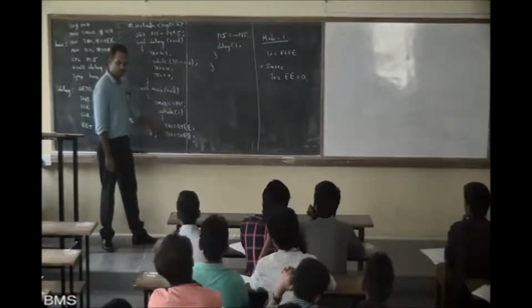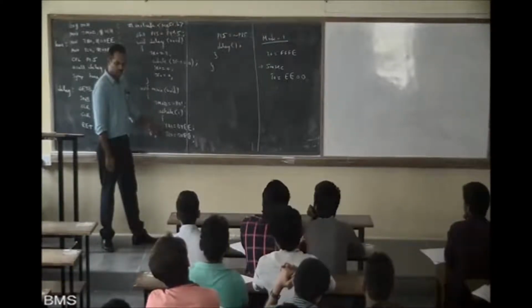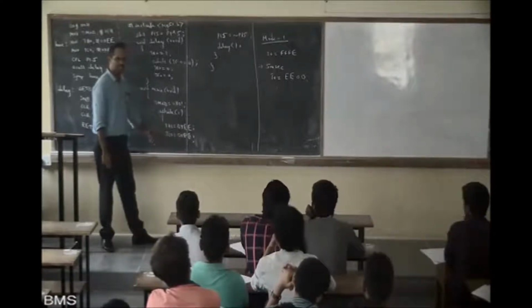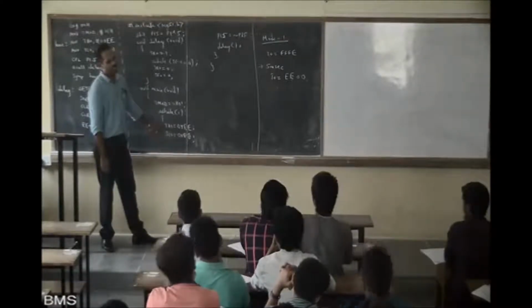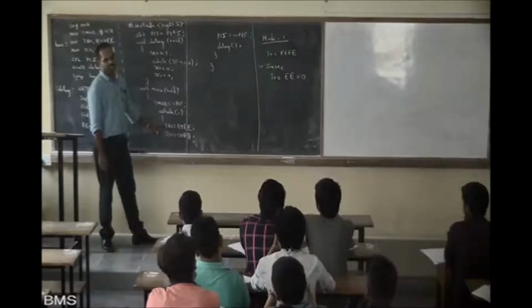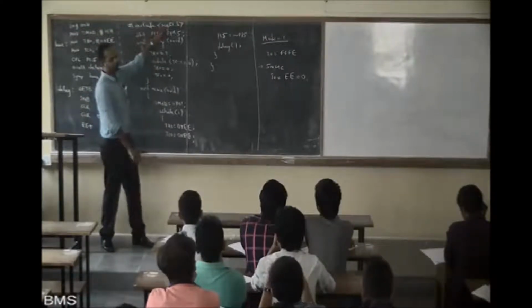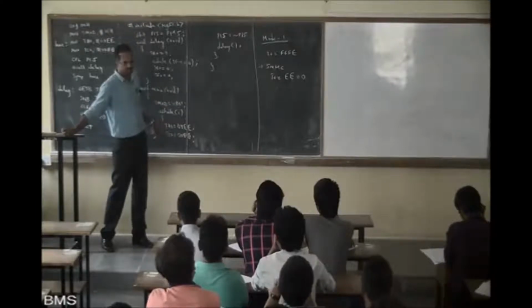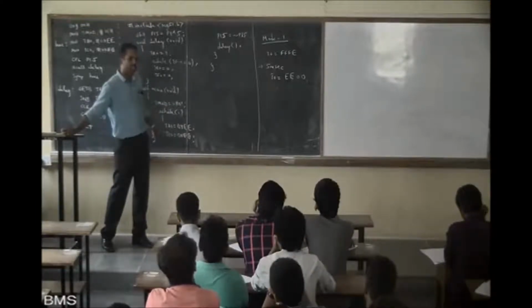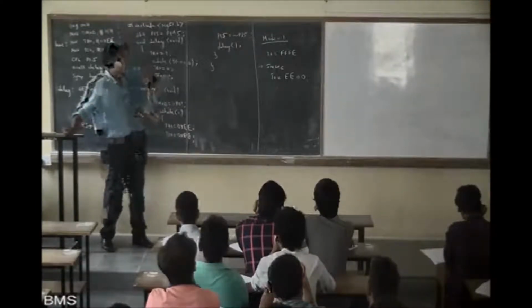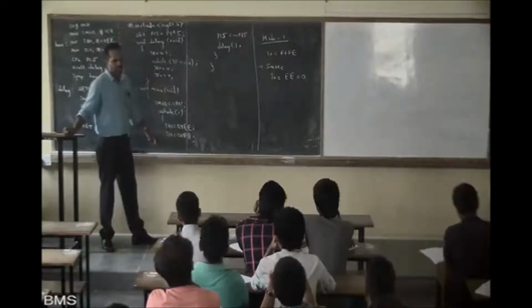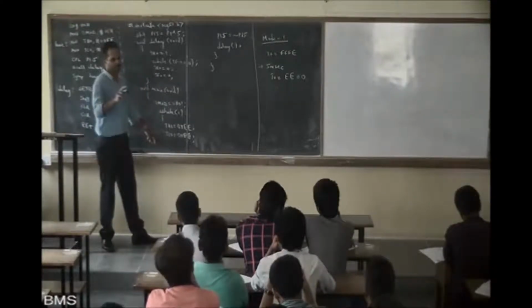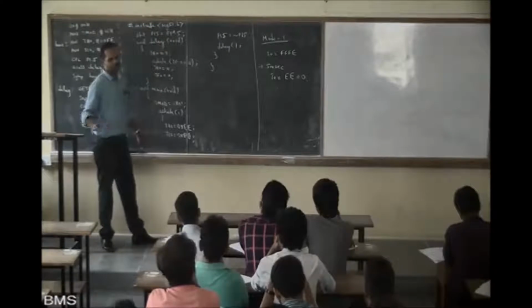T0? We are using TH0, TL0. I don't think T0 is defined directly in the 8051 register set. We should check that. If it is defined, you can use it. Because TH0 and TL0 are standard registers in the SFR, T0 is a combination of these two registers. I don't think it will be defined. If it is, you have to check, and then you can use that.